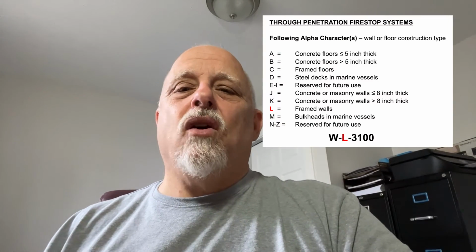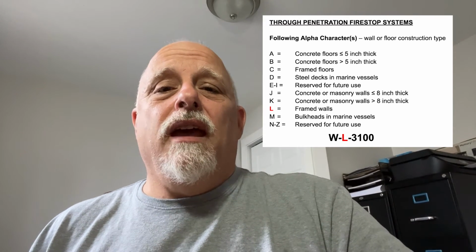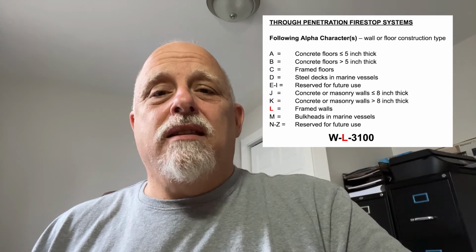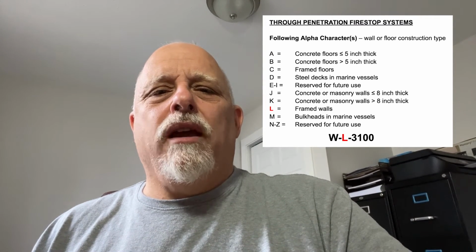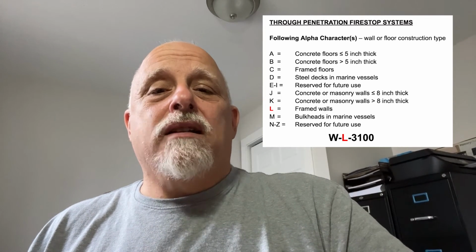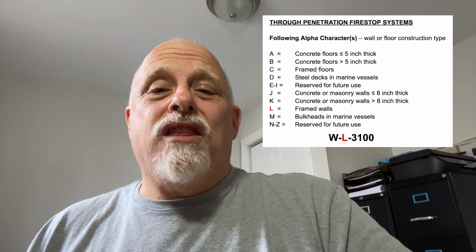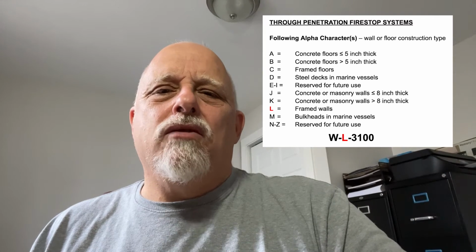Our second digit is going to be L, because remember it's WL3100. The L tells us what it is that we are penetrating, right? The L indicates that it's a framed wall. There are some other indicators as well. They use the alphabet letters A through Z. N and Z are reserved for future use. Had it been a letter B, then that firestop system would have been rated for a concrete floor with more than 5-inch thick flooring. So that second digit tells you exactly what it is that you're penetrating.